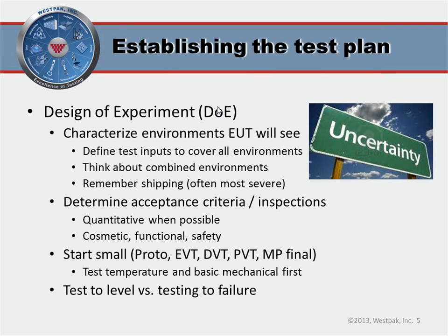You can think about some examples. Mike mentioned vibration and temperature, for example. The U.S. military found out years ago that they could reproduce field failures by using this type of test, which they refer to as shake and bake, that could not be reproduced with other environments. Westpak has found the same thing. We do one particular test for a product as simple and mundane as ice cream, and that involves three inputs: temperature, vibration, and altitude, all of which have a potentially disastrous effect on, yes, ice cream. So think about combined environments in a way that is creative, and most often, if you're uncertain about reproducing in the laboratory known field failures in previous products or even in the existing product.